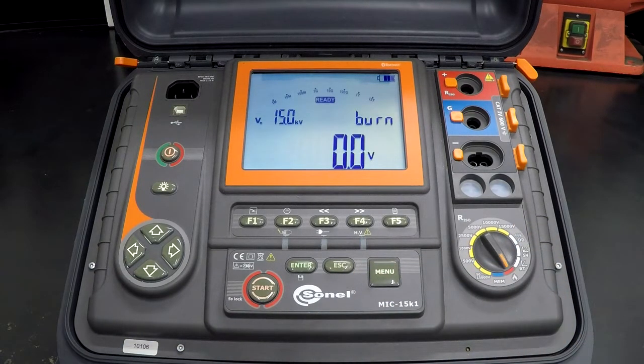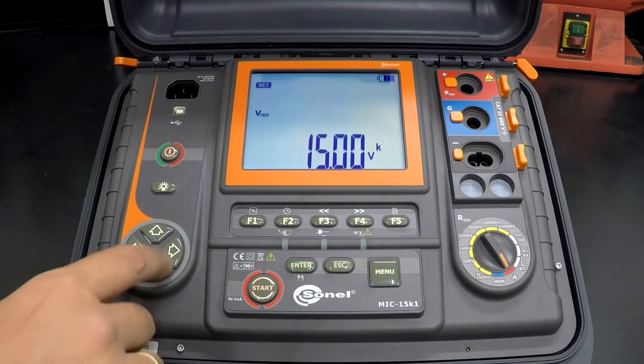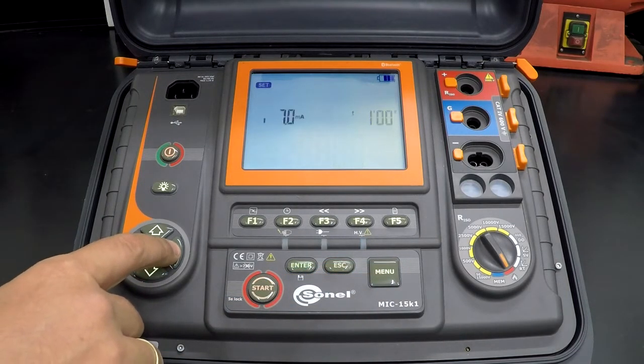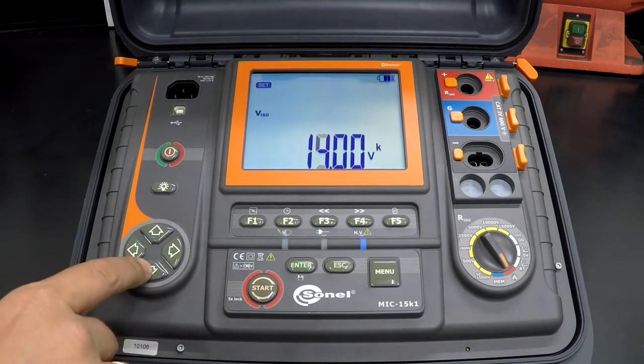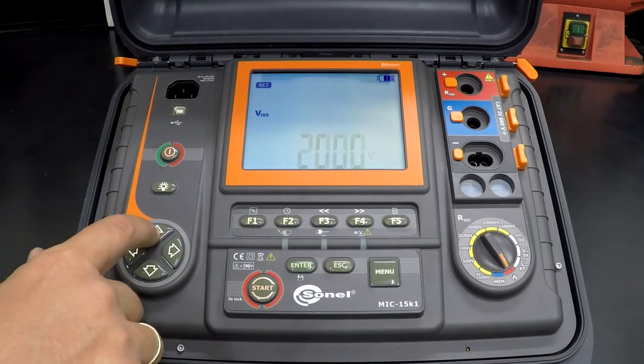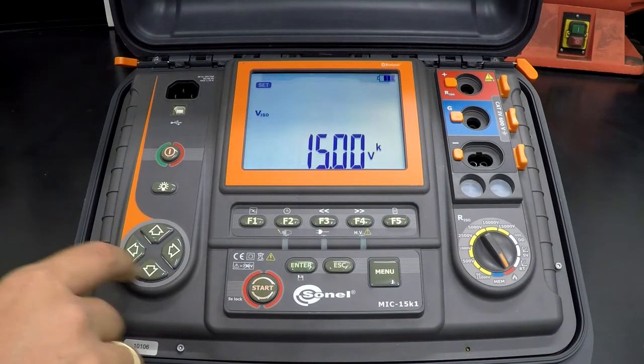The next method is the afterburning method. The meter carries out the measurement as for the isolation resistance, except that it's not interrupted at the breakdown. If a breakdown occurs, the measurement is continued. During this time, you can find the place of damage breakdown.